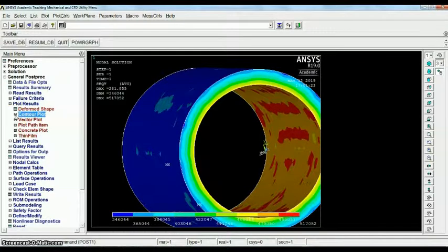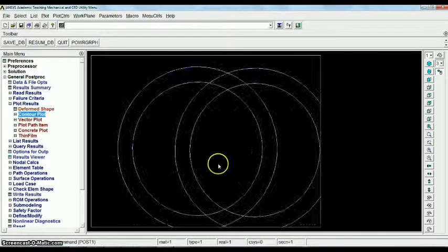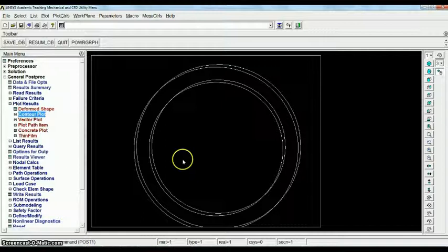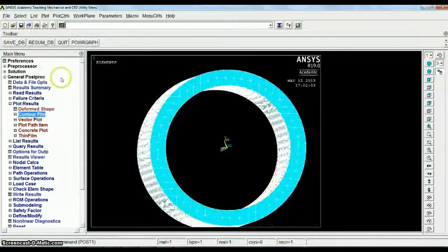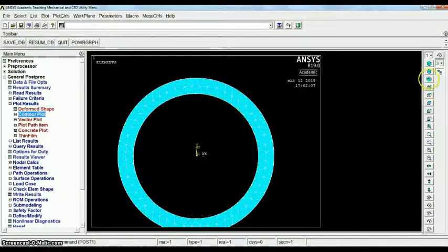Now let's use this to get the circumference stress on circumferences here in the middle of the diameter, between the inside diameter, inner diameter, and outside diameter. We want to see the stress distribution, or stress concentration, along the midpoint of this thickness of the pressure vessel. So to do so, let's go to plot elements, get side view like this, better fit.